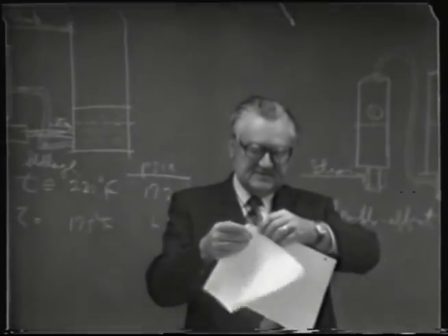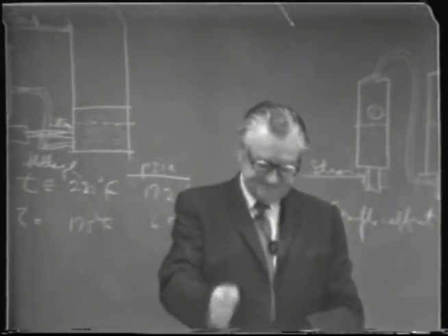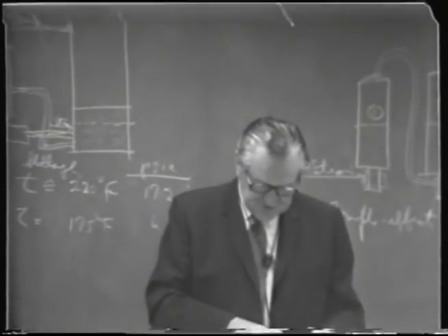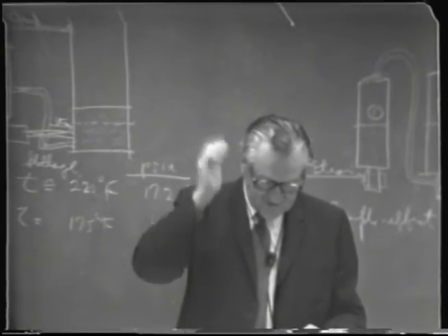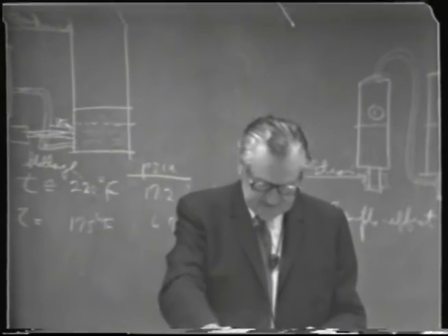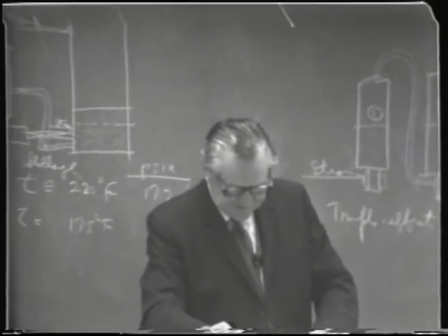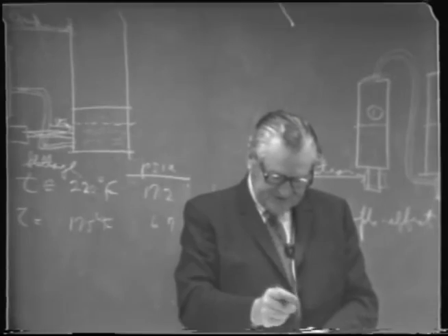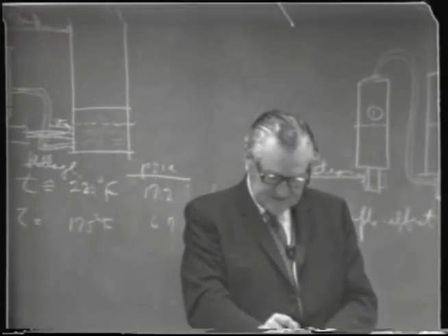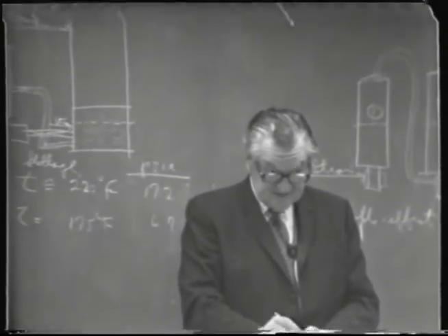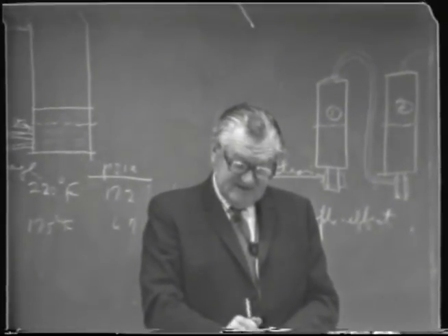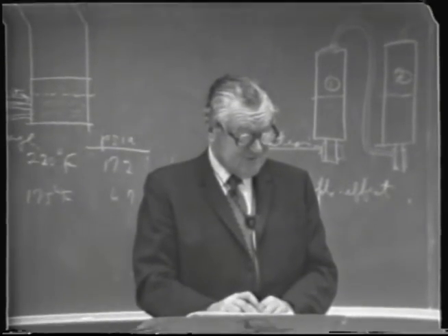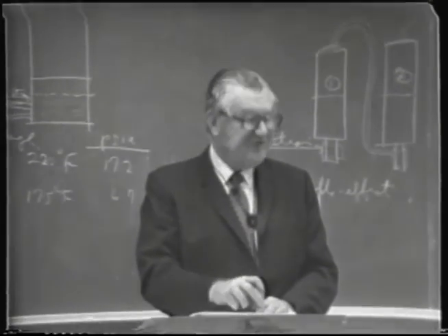Finally, last, no, not quite the last, the figure F shows another design that was used in that very large column I referred to last time. Showed a little drawing of it, of the one down in Madeira, which incidentally had 70 plates total in the column, not 70 plates in the stripping section, as I read off. In other words, it had 20 plates in the stripping section and 50 in the concentrating section.